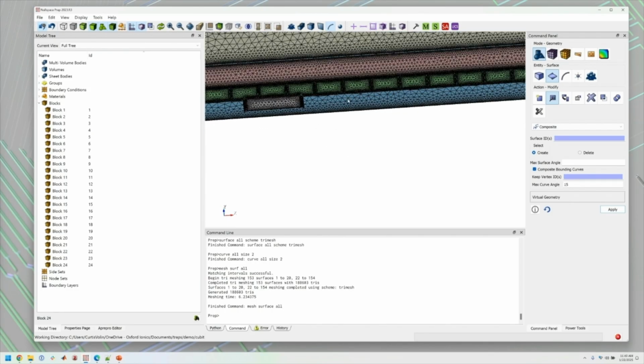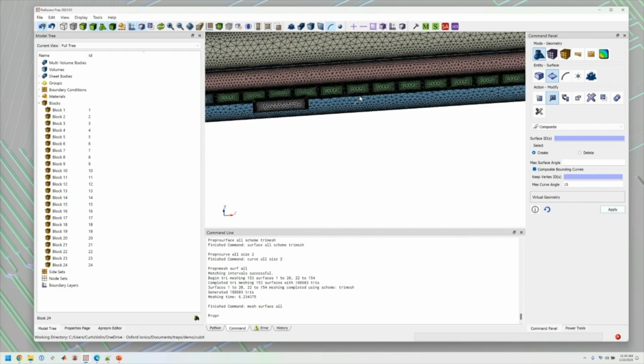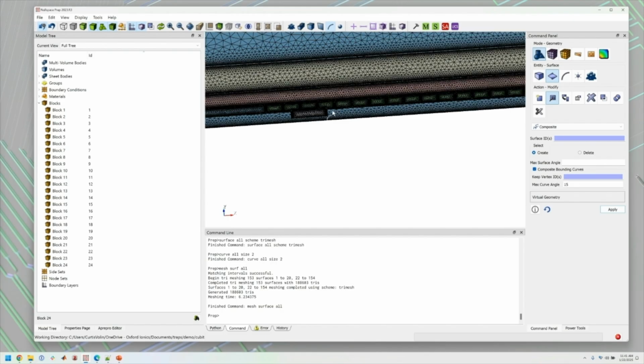That when I go in and try to find, for instance, the RF null in this case, that it will be located perfectly at y equals 0 to numerical precision, as opposed to sort of wandering around at the fidelity of the model, which, I'll show you later on, is quite good, but it still gives you a little bit of an advantage there.